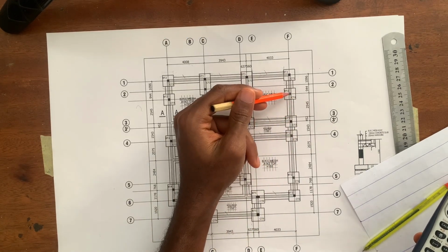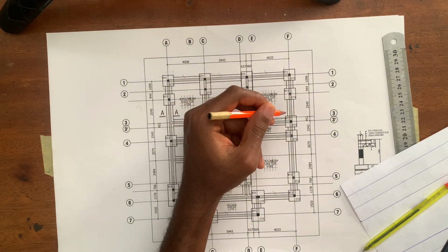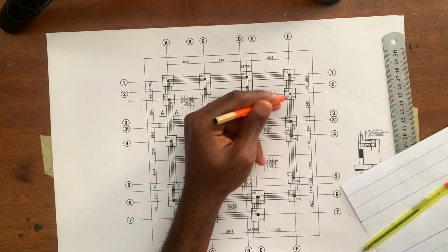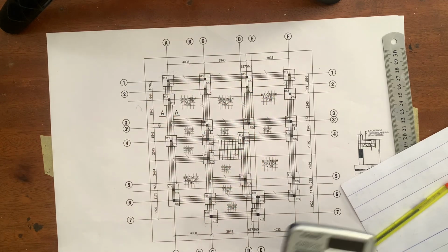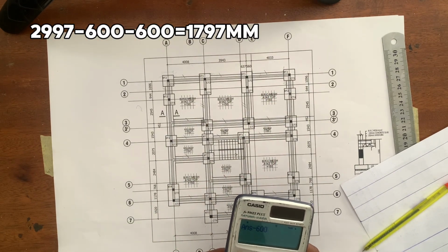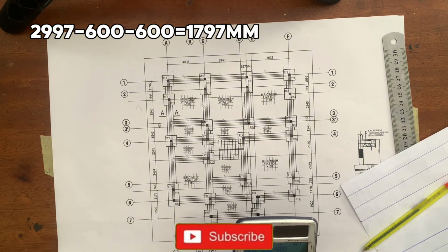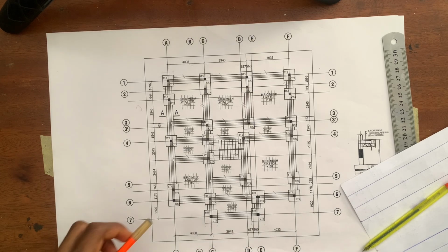So the distance from this call out to call out 3 prime is 2997. We're going to be minusing half of the length of base type 2 from both sides. So 1200 divided by 2 is 600, and we're going to minus 600 from the two sides. So 2997 minus 600 from one side, minus 600 from the other side, will give me 1797. So we're going to book.